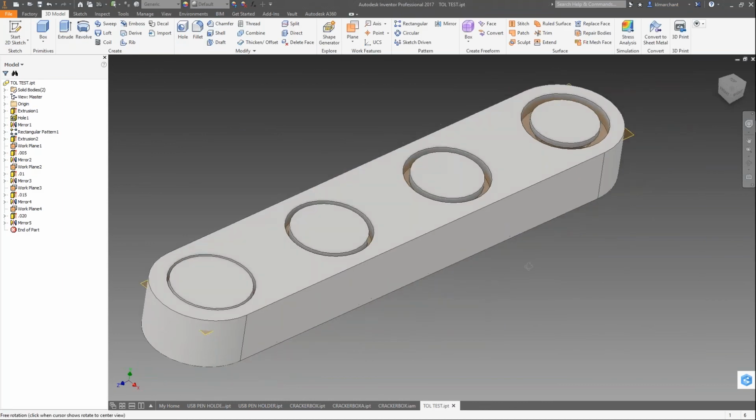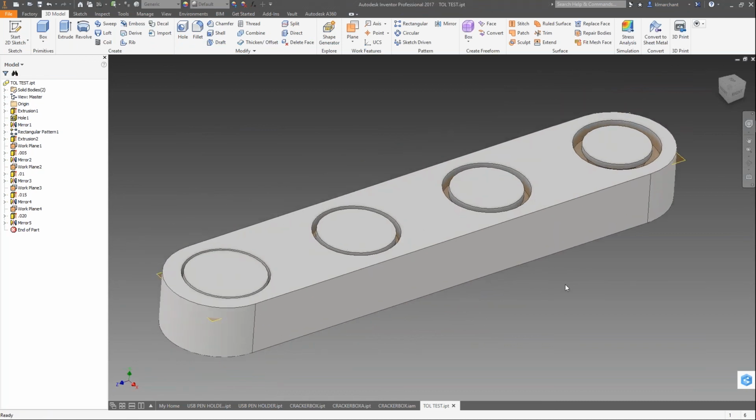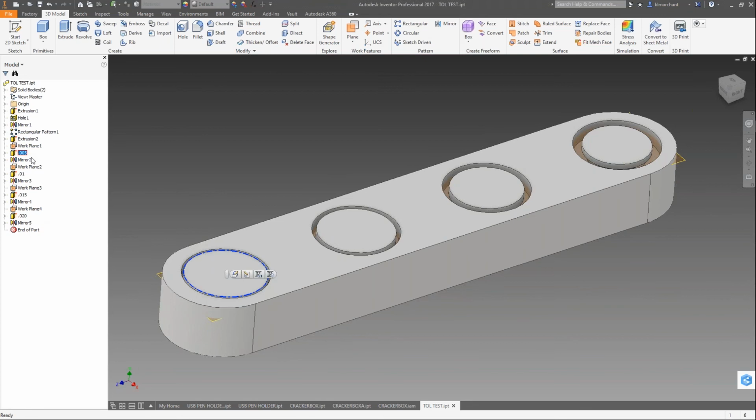And so we can design with that knowledge of our resolution, because I know if I've got a smaller resolution, A, I'm going to pick up this corner better, and B, I'm going to be able to get a further point on my contact surface out here. So resolution is one thing that you want to pay attention to, want to be aware of while you're printing and while you're designing.